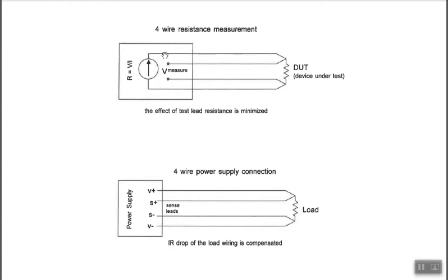They're going to have a test probe that looks like 2 leads, but inside there's 2 wires in each lead, and there's 2 wires going to the same place, which again makes you think, well, why? And here is the why that we mentioned way back at the beginning of this video. The why is because 2 of the wires are going to carry current, and 2 of the wires that also are redundant, it seems, they go to the exact same spot. But these 2 wires do not carry current.